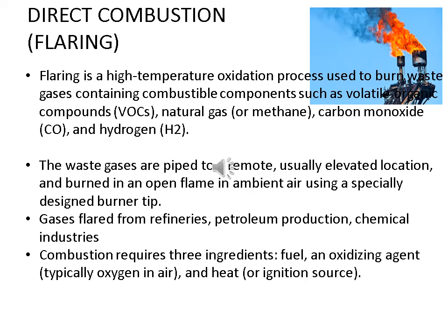Mainly refineries, petroleum production companies, and chemical industries adopt this type of flaring method to remove these waste gases. The working principle of this method is that the waste gas is piped to a remote or usually elevated location, at an elevated height of 10 to 25 meters, then burned in an open flame.